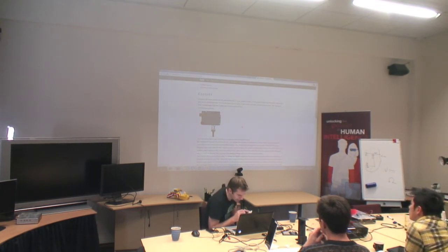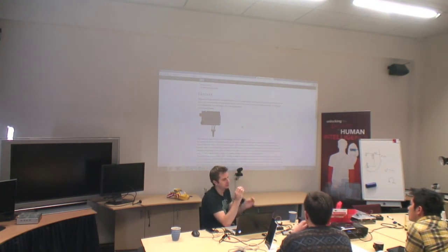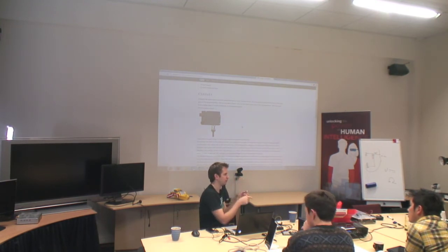And what we want to do now is put voltage plus into one side of this. So these potentiometers or variable resistors have 3 legs. The leg on the leftmost side or the rightmost side, it doesn't actually matter because they work in either direction, will be the minimum voltage, so usually ground. The pin on the other side will be your maximum voltage, so 5 volts or whatever, and the pin in the middle is the sense pin, so that's the pin you're going to connect to your analog read.